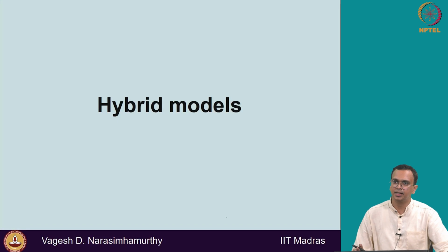So this is the grid guidelines and some estimates for LES, and you need to do some sensitivity study. You need to figure it out, right? And there was one problem that I discussed with LES, which is wall. Whenever a wall is coming in and a boundary layer is getting developed, it is posing a challenge for computational demand. You need to resolve the wall in aerodynamics and heat transfer and such problems. Then it's computationally very expensive.